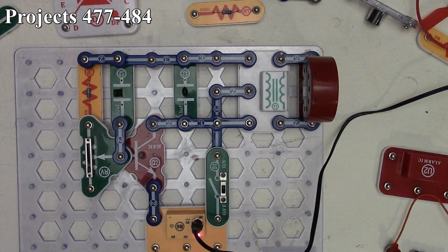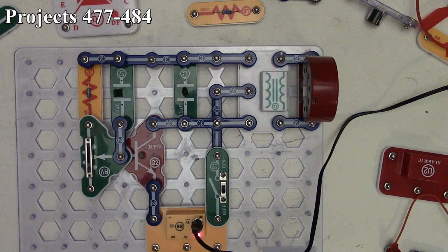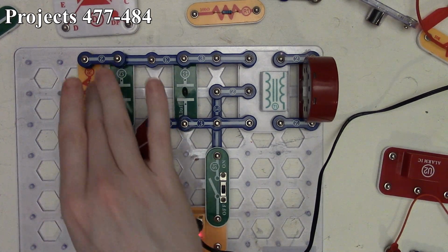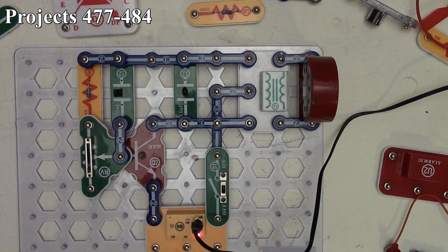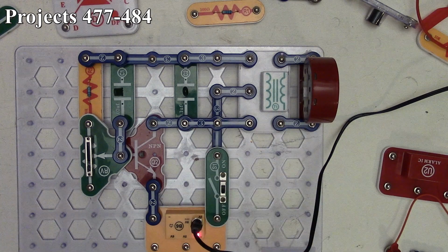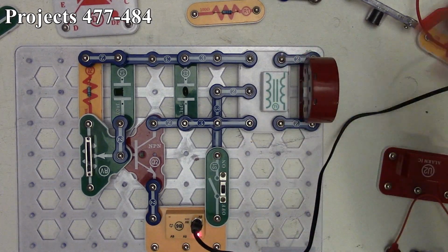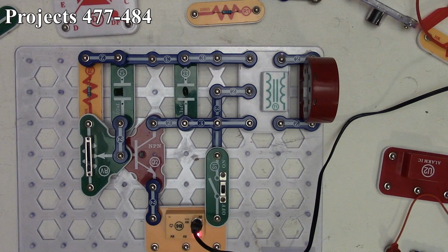So we got our transformer outputting to our speaker, using our C1 and C2 capacitors for coupling, along with our R5 100,000 ohm resistor feeding our variable resistor, which is connected to the base of our NPN transistor, which helps again produce the oscillation effect by turning the NPN transistor on and off, which then creates our signal for our transformer, and then it outputs to our speaker.